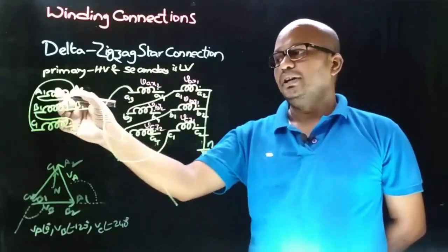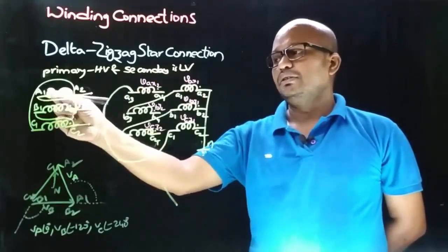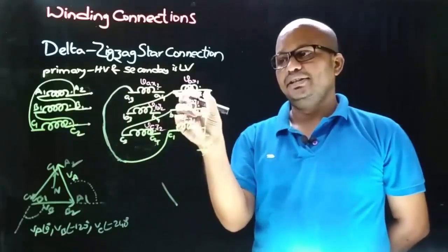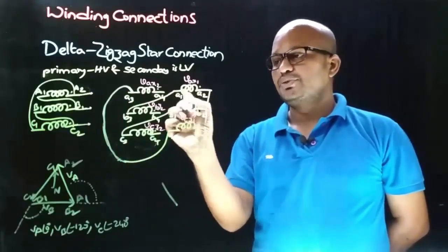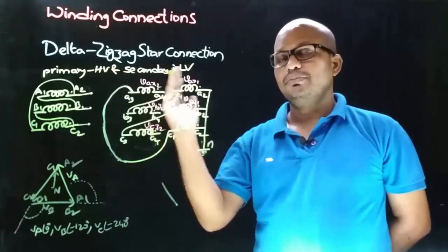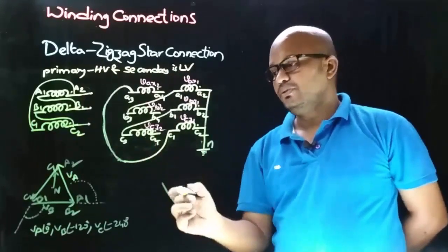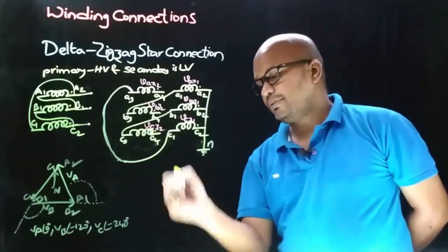And observe that on primary side the connection is took from dotted terminal, and coming to the secondary side in this coil, connection is took from non-dotted terminal, means the secondary side phasor direction is opposite to primary side phasor. So VA X1 phasor direction will be like this.